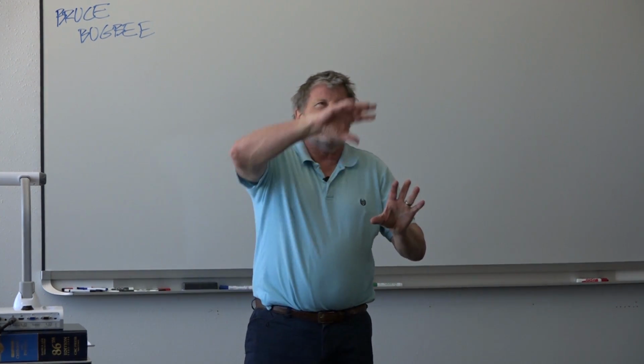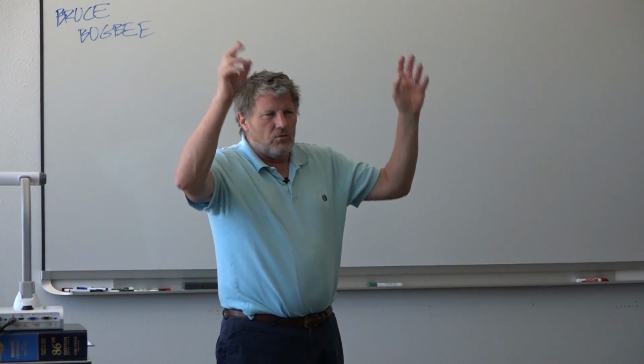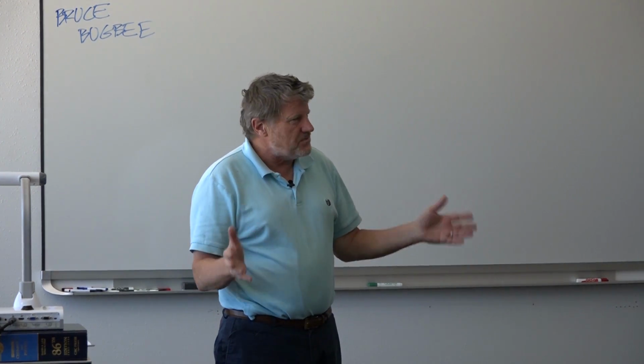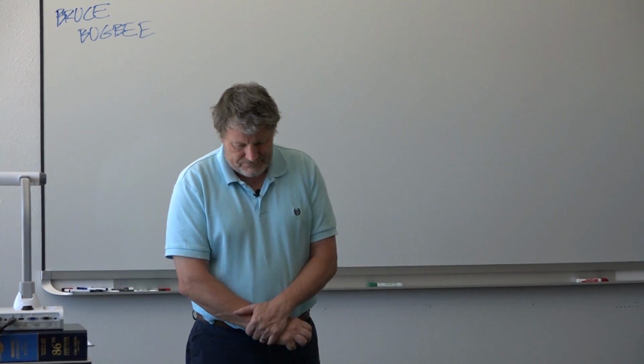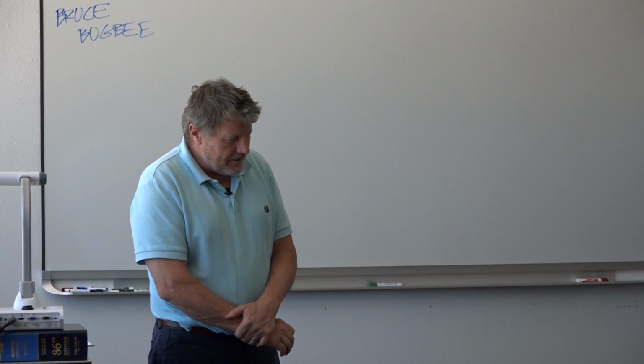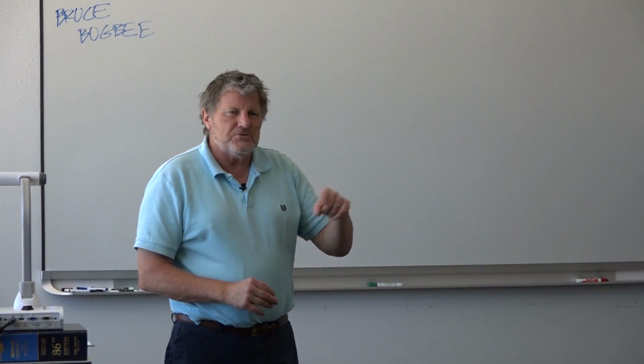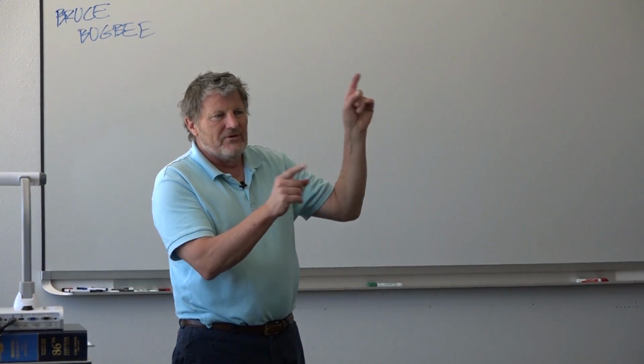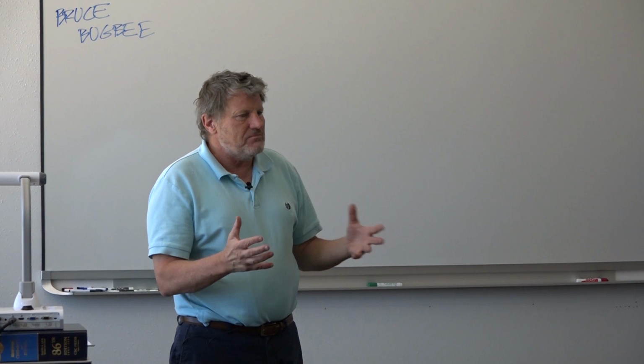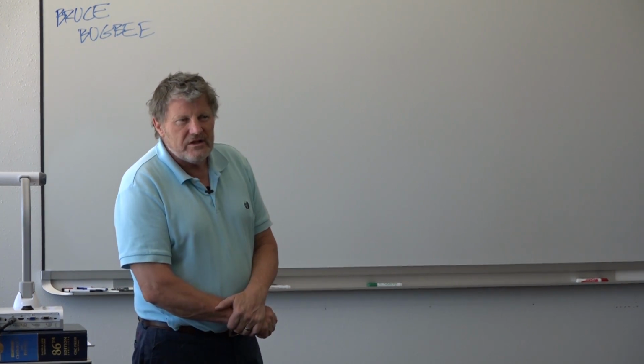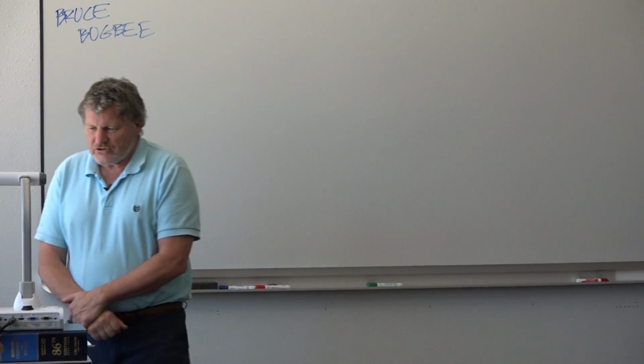We can do things like eddy covariance to get water transfer, and that's expensive and requires knowledgeable people, and that's still an indirect measurement of measuring water vapor. So we keep coming back to energy balance principles to really understand where the water is going.